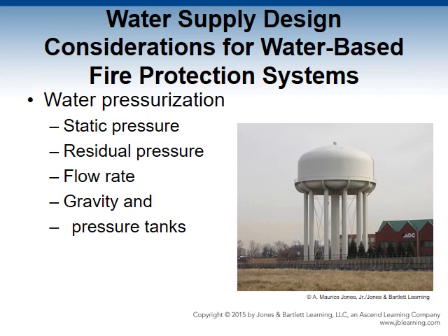Water pressurization. Whether pressure is constant or varied within the system, the fire protection system design professional must determine if the pressure is adequate to support the design in that part of the community. The system design professional must know the static pressure and residual pressure, as well as the flow rate at the residual pressure. If the residual pressure is determined to be insufficient, installation of gravity tanks, pressure tanks, or stationary fire pumps can support the municipal network, water supply, or natural resources.